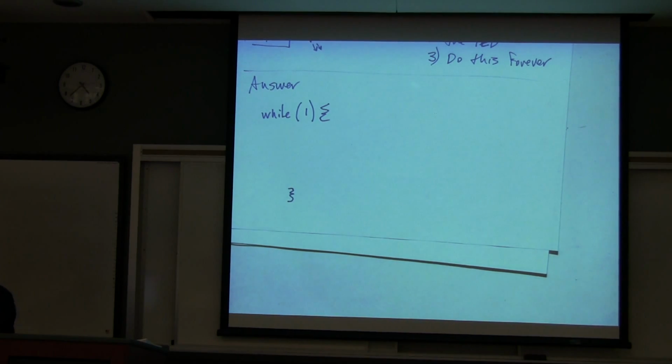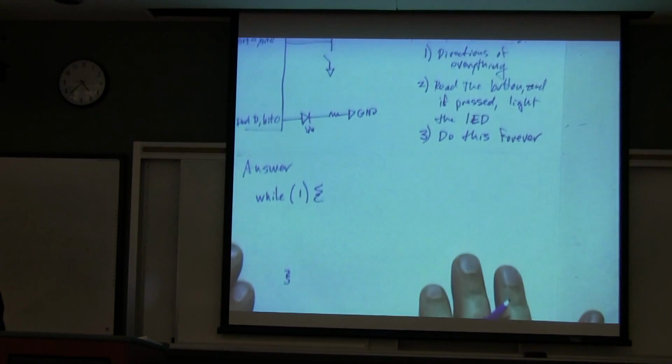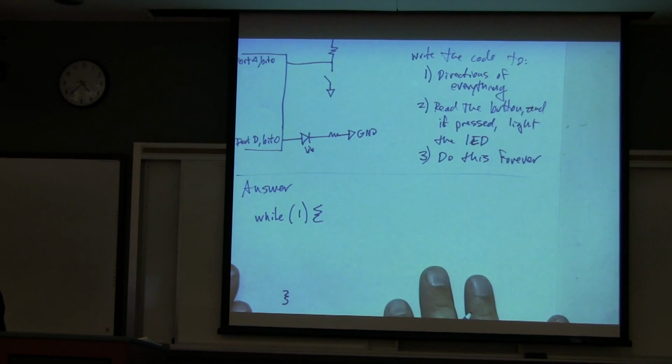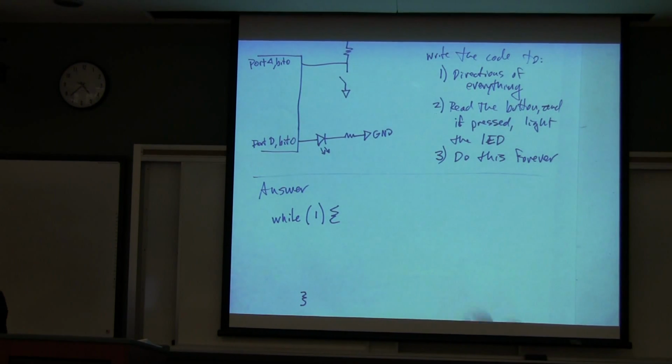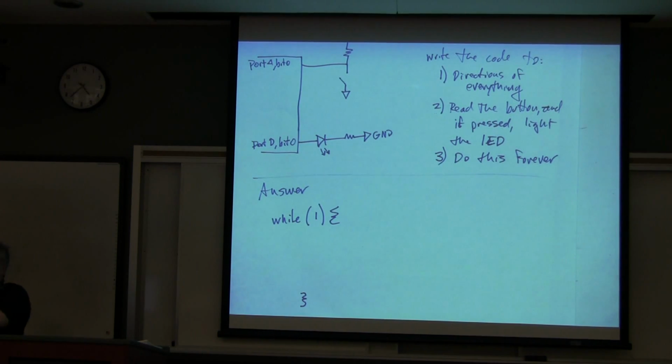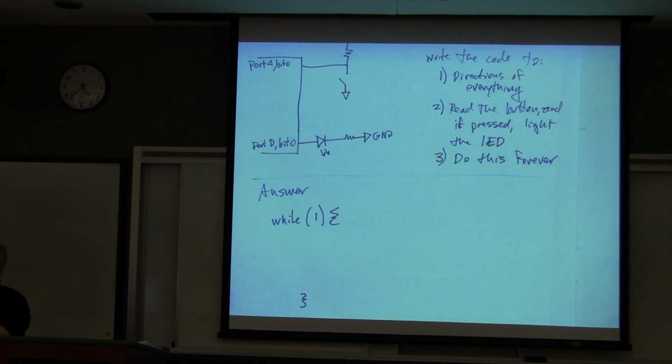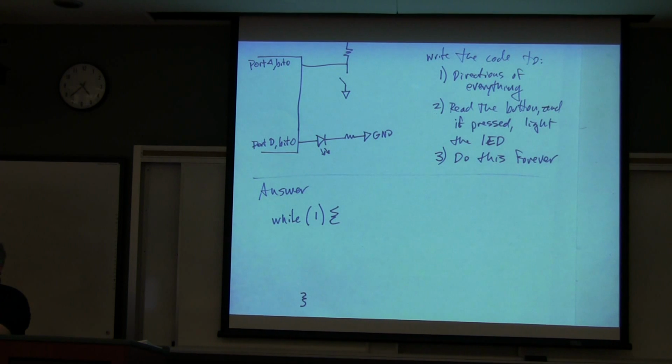Is it super bad if you put the direction in the while? No. That's not bad. But unnecessary code will be executed all the time, right? That'll mean it executes all the time. Is that bad? For our simple machine, no. But when you're doing a real embedded system, yes.